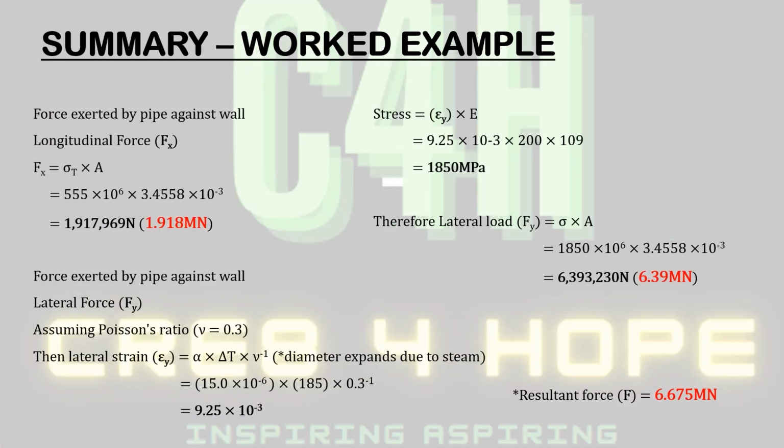So let's look at a situation where some form of lateral force is being generated, if we're assuming that there's that possibility of the pipe being constrained, and that's going to cause excessive pressure buildup. Now, normally we could use the appropriate formula for stresses in cylinders, calculating the hoop stress and the radial stress.